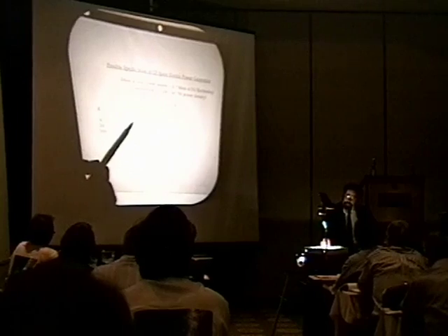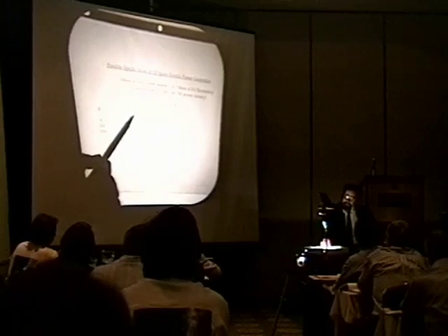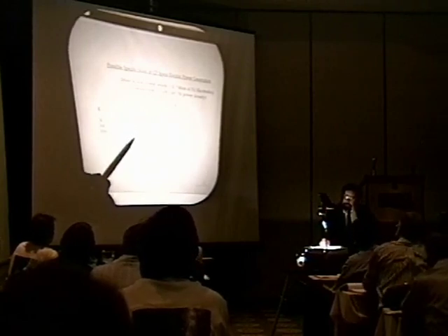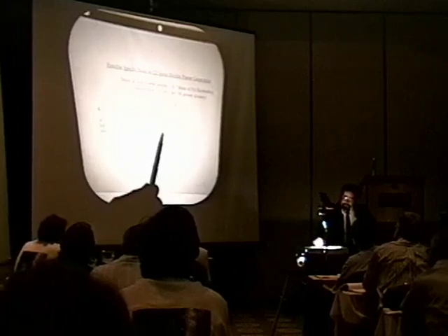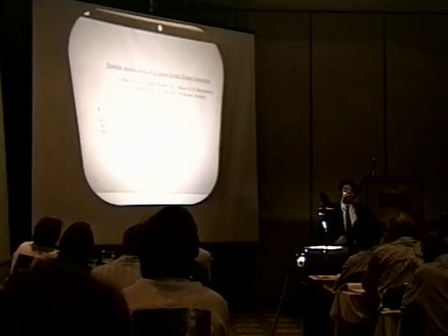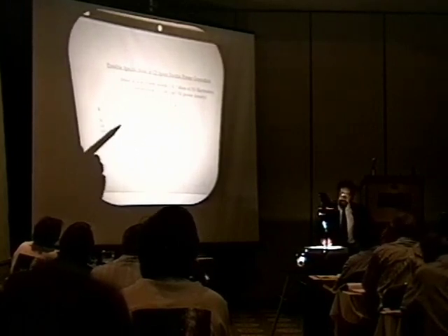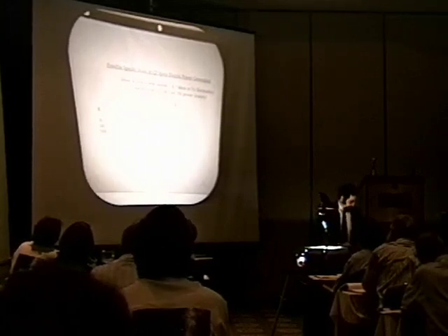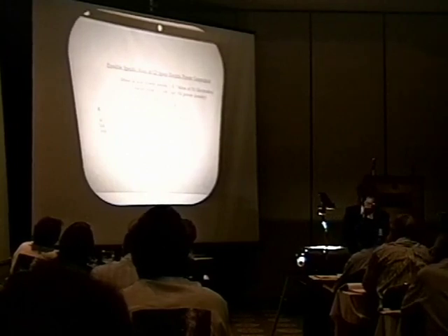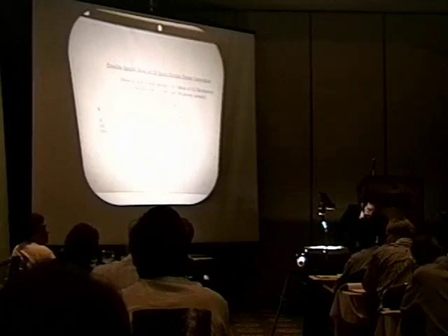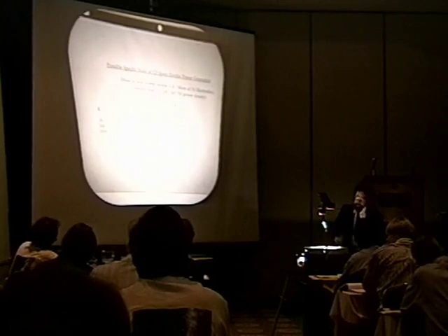It might be possible to have specific masses of the electric power source for the ion engines in the range of 4 to 40, or perhaps if we have higher efficiency of conversion, even much lower. The current technology is about 50 kilograms per kilowatt electric. I don't know whether these numbers will ever be achieved, or perhaps they're too conservative, but it seems to me that since we don't have shielding requirements for cold fusion reactors, unlike the SP100 reactor, which is being built, planned, what have you, it'll be a lighter power source.